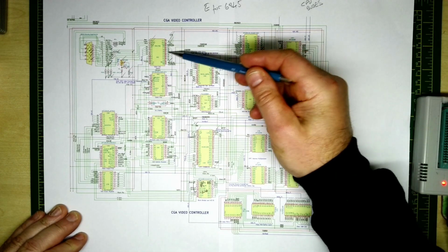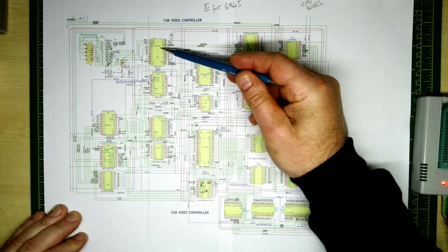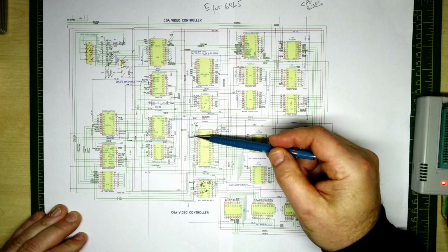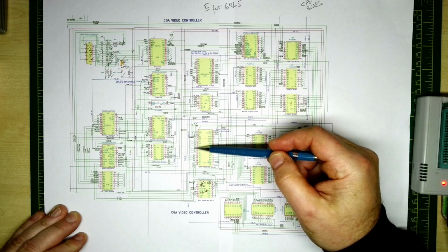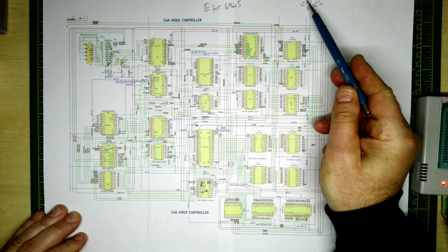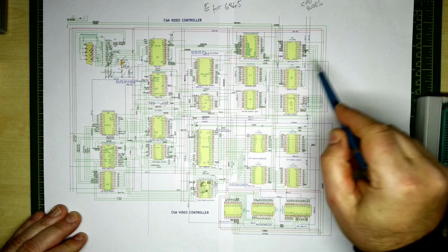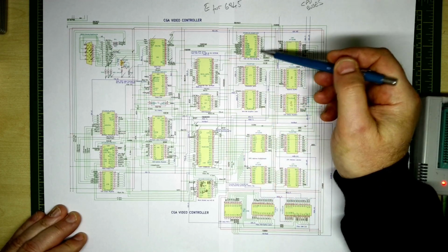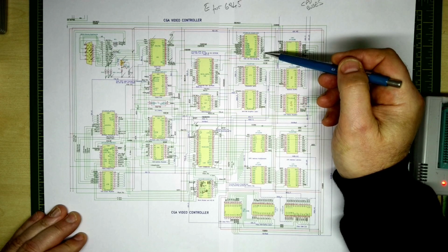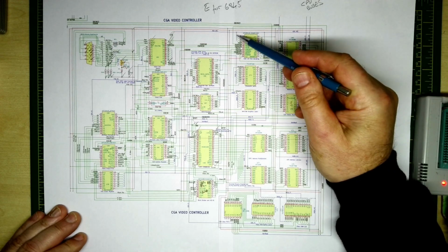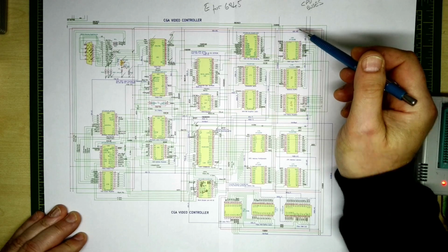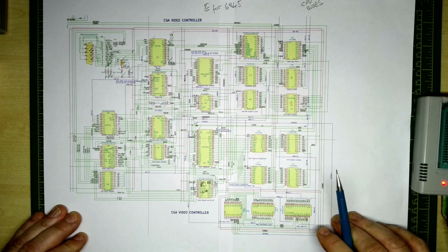So we're going to need to connect the data bus for the video DAC here down to the CRTC. I'm going to just get a cable off the CRTC to go to the CPU bus initially. It's going to be wired up to various buffers and things a little bit later. And then we just need to also connect the address bus and the IO read, IO write over here to the CPU buses, and then that should allow us to plug this into the main board and start testing it.